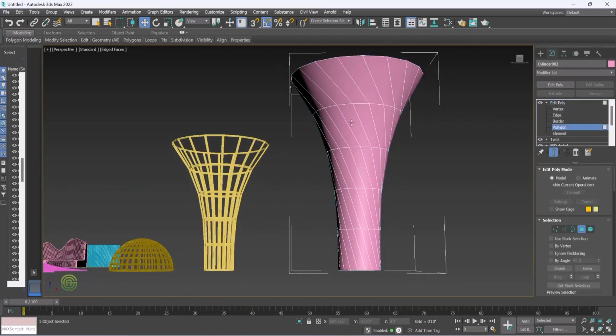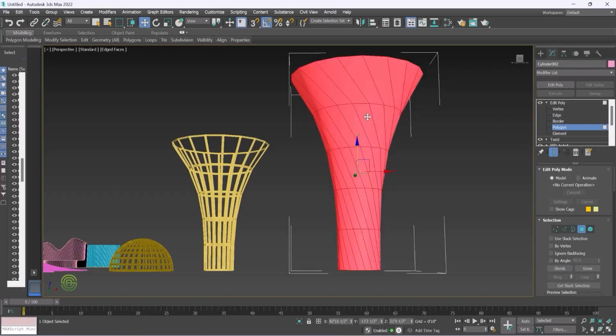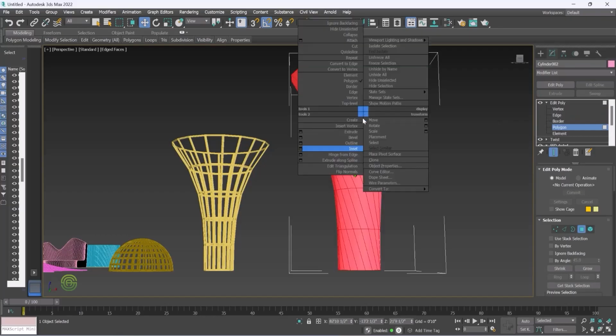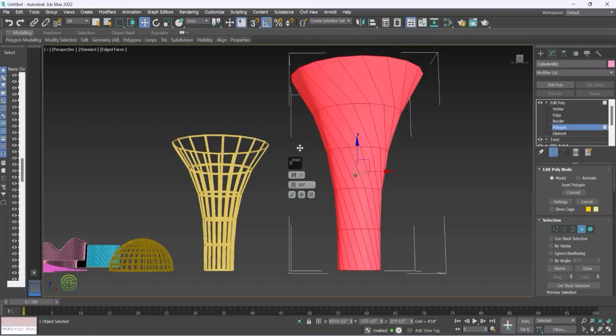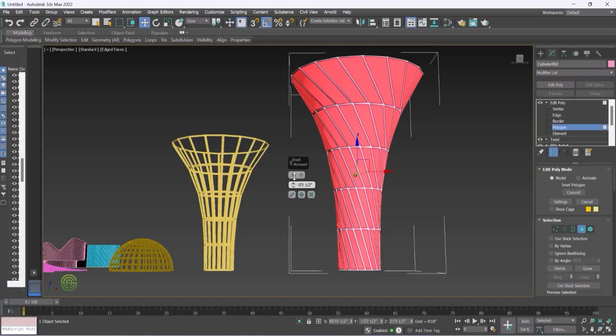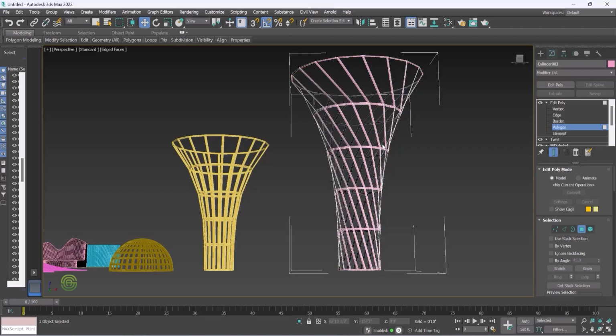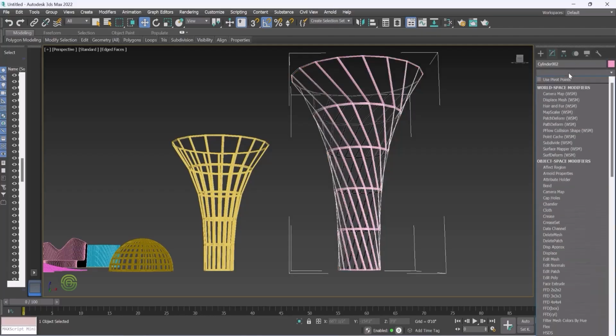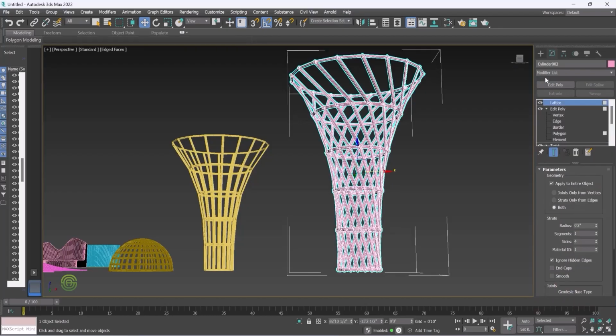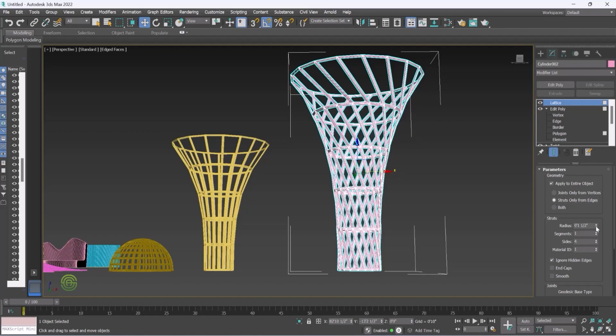First go to polygon, select any one of the poly, press Ctrl A to select all, and give a right click, insert by polygon, give a value. Okay. Now delete the rest. Now go to modify, press L, lattice. Just click struts and just reduce the thickness.